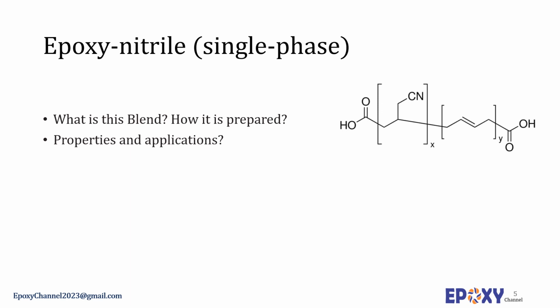The nitrile component is introduced into the epoxy resin at elevated temperatures. The blend is cured with standard epoxy curing agents and catalysts at elevated temperatures. Nitrogen-containing curing agents are generally used with these modifiers because they catalyze the reaction of the carboxyl group with the epoxy functionality. Relatively high molecular weight rubbers, bigger than 20,000, are used. The final product is generally an adhesive solution or an adhesive film.